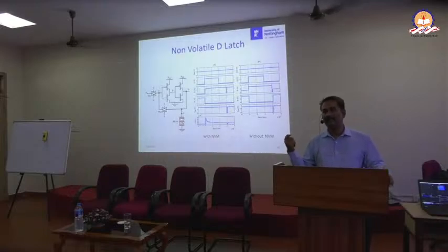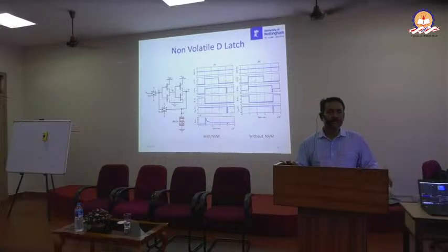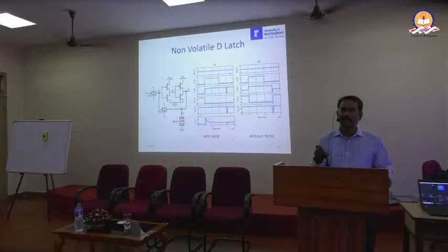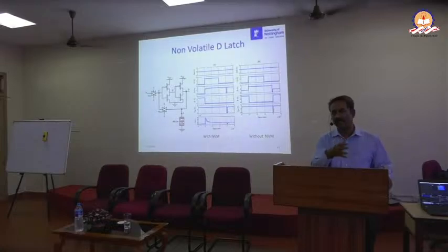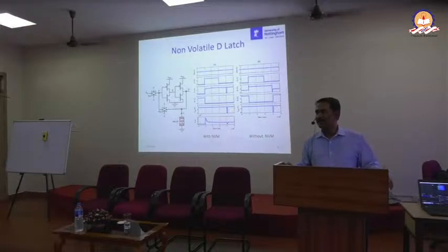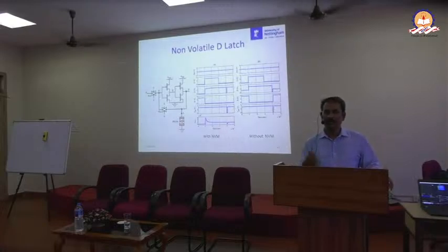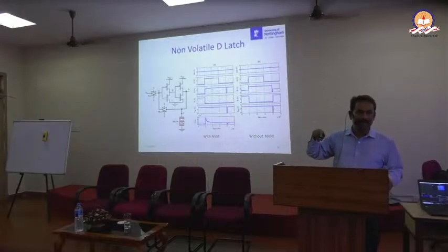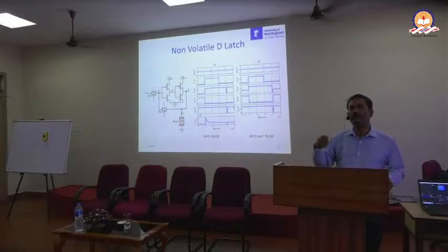An application for this, I can say, is in space. There is a lot of radiation there, and when you subject electronic devices to this radiation, it can actually change the memory state of the devices. Not only in space, even in nuclear plants, or places like CERN where they are testing, the electronic devices are susceptible to this kind of effect. What they do is use a one-time programmable device. So you program it once, that's it, you cannot reprogram it. But here, if you incorporate the memory inside, like non-volatile memory, it's possible for you to reprogram it. That's the concept that we would like to bring in here.